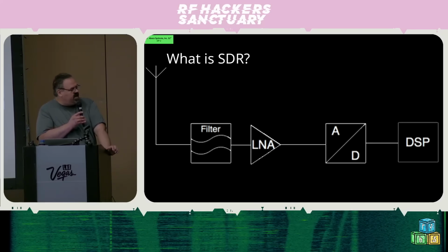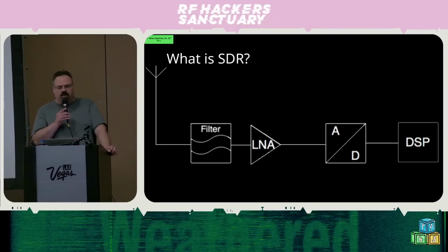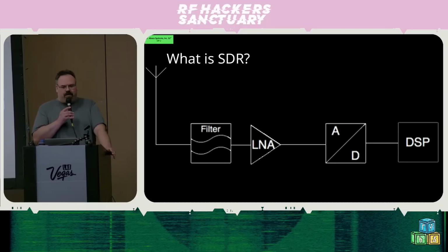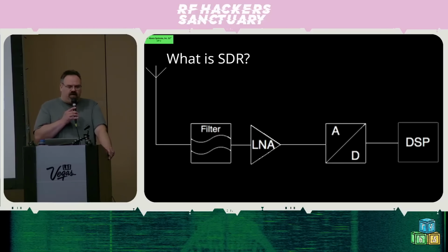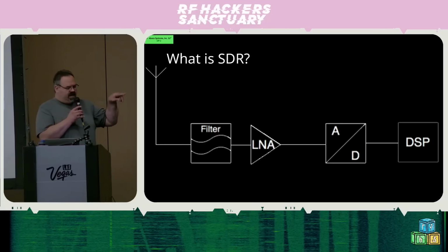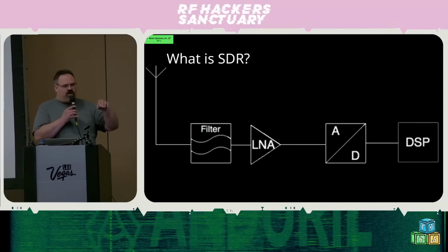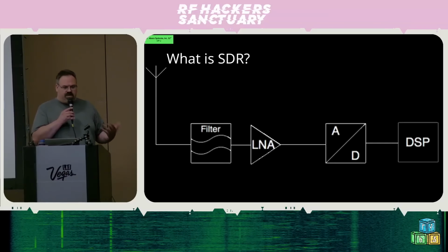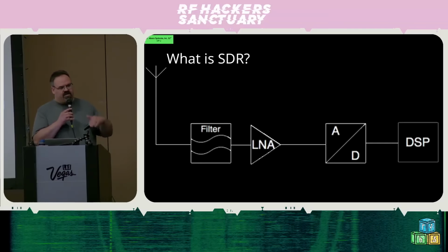This is a low noise amplifier, so called because it is an amplifier that does not introduce much noise. Whenever you amplify a radio signal, you aren't just amplifying the one little bit of whatever you want. You're amplifying everything, and that includes all of the background noise. And some of the characteristics of these devices is that they introduce additional noise, which can actually overwhelm your signal. So you want a specifically designed amplifier that does not introduce that extra noise so that you can actually see what you want to see.